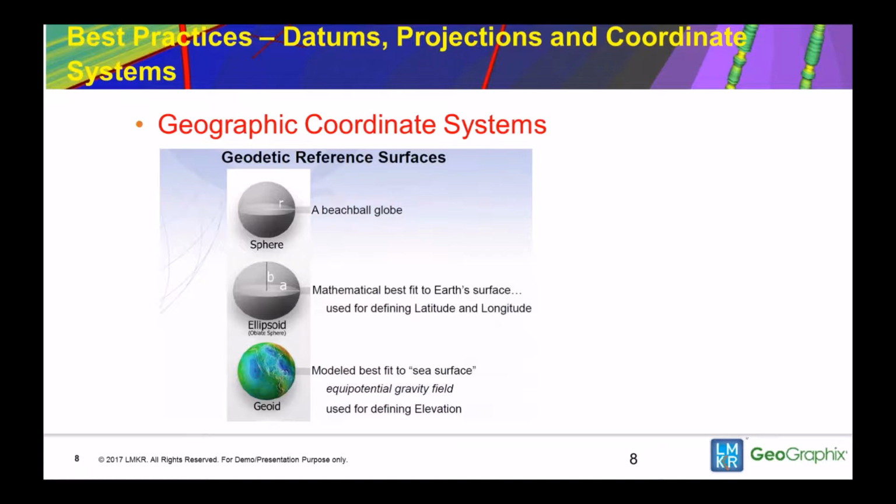So whenever you look at a PRJ file or you look at a well-known text file in Esri, that ellipsoid, this is what it's actually defining. So in order to create an ellipsoid, you have two radii, I suppose, a semi-major and a semi-minor axis, one from the center of the Earth to the pole, and one from the center of the Earth to the equator.